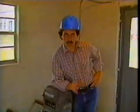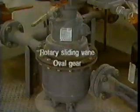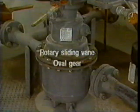Now that we've seen the basic components of the positive displacement meter, let's look at two meters, the rotary sliding vane and the oval gear. The rotary sliding vane meter consists of a single or double case housing, a cylindrical rotor which revolves on the ball bearing around a central shaft, and a stationary cam. The rotor has 4 or 6 evenly spaced slots which provide guides for the blades.